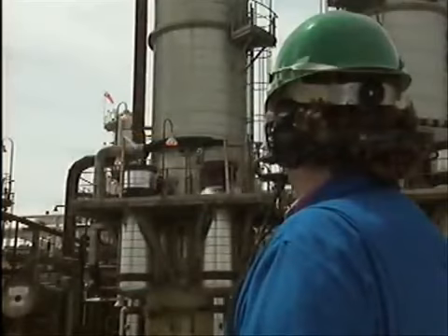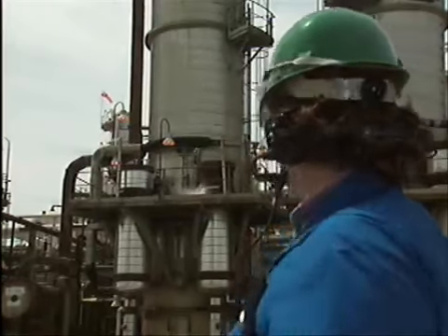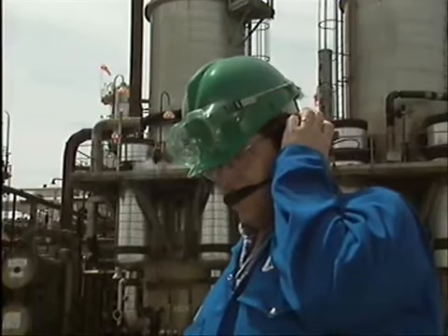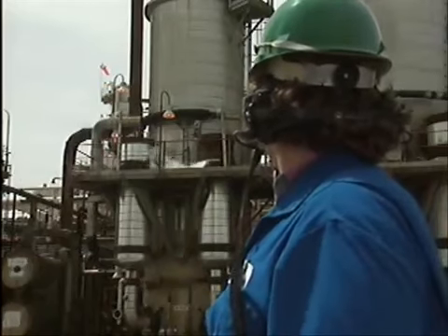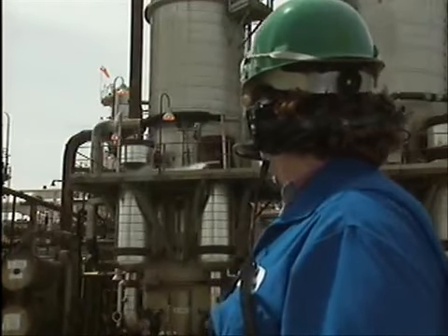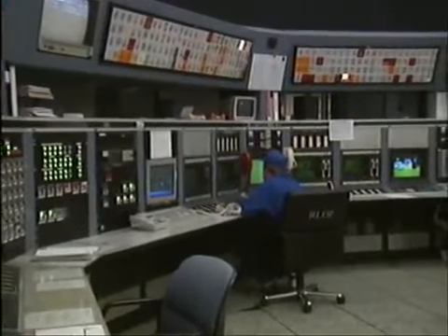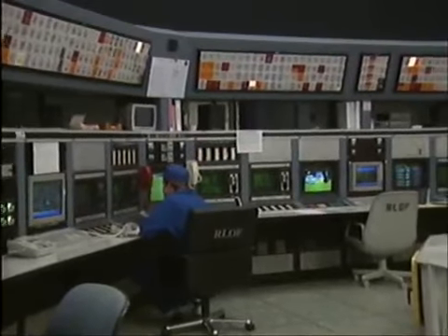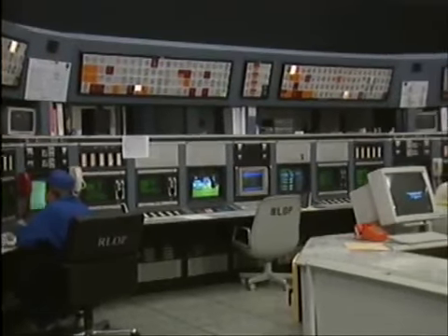properly. But any time a safety valve is lifted, there's a corresponding drop in system pressure. So before you hand lift a valve, notify the appropriate operating personnel so that they can compensate for the drop in system pressure and keep it from interfering with normal operations. If operating personnel aren't forewarned, when pressure drops as you hand lift the valve, they might take emergency measures to raise pressure or to shut down the system. Such actions could be costly and perhaps dangerous.